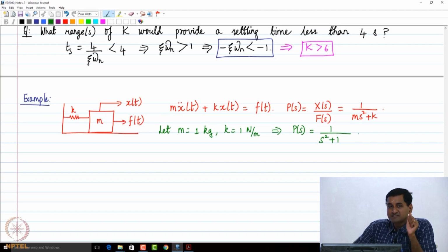So, what did we discuss? If you have non-repeating poles on the imaginary axis, then for one class of inputs the system output is going to blow off to infinity. So, in this example, for what input will your system output go to infinity in magnitude? Cos t and sin t. So, for imaginary roots, if you have a sinusoidal input whose angular frequency is the magnitude of the pole, our output magnitude goes to infinity as t tends to infinity. That is what we have.